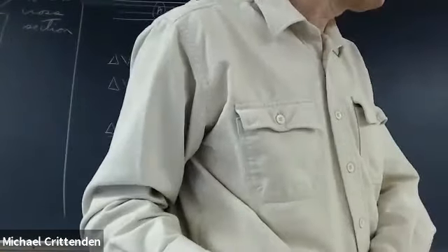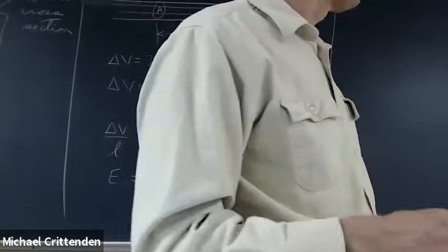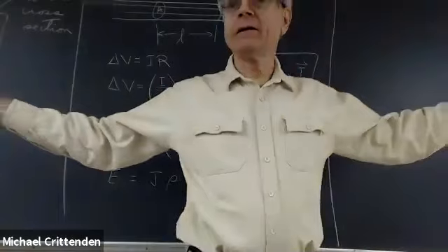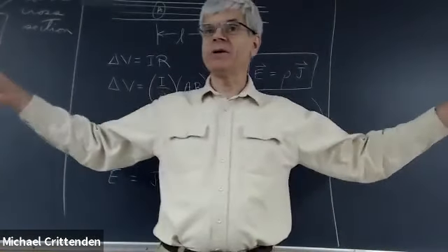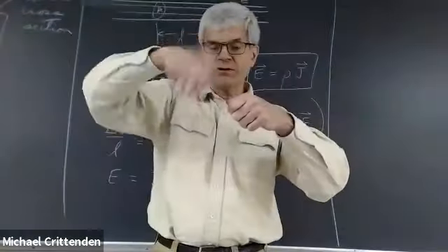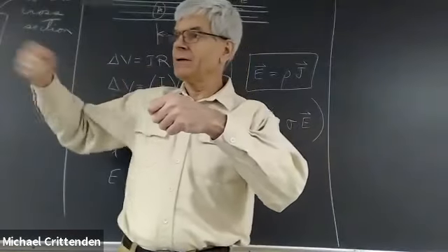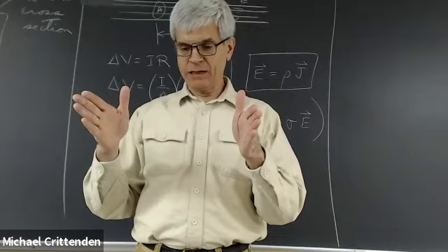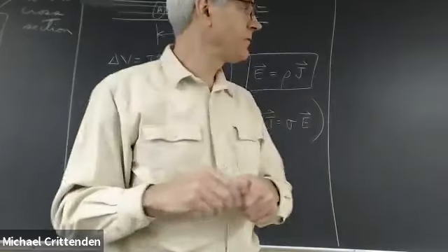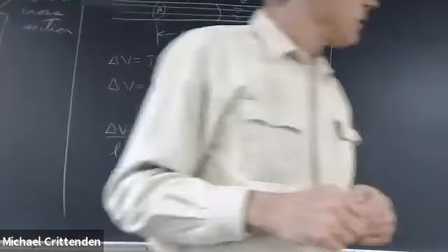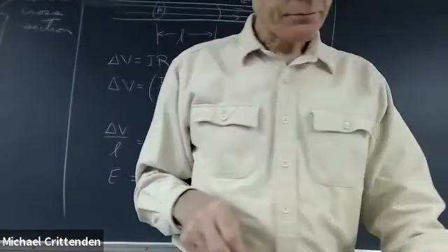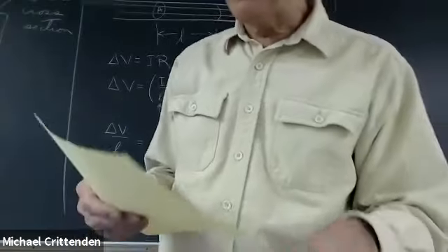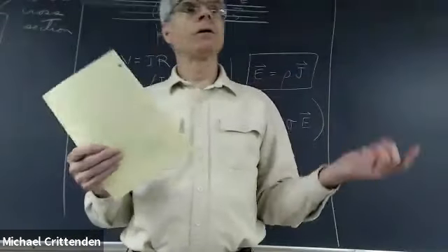You've got the heating element, as I said, is a piece of nichrome wire. 2 meters might sound kind of long, but of course it's all coiled up. You get something like a wooden dowel and you just wind the wire around it like that and it makes a nice little heating element about that long that fits in the toaster oven just right. 24 ohms.